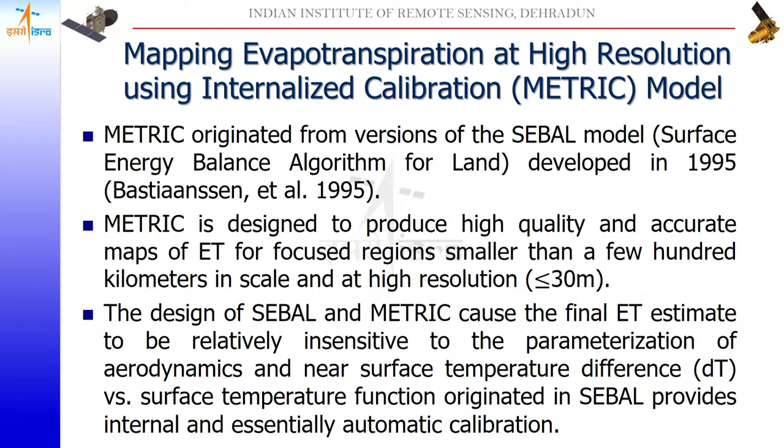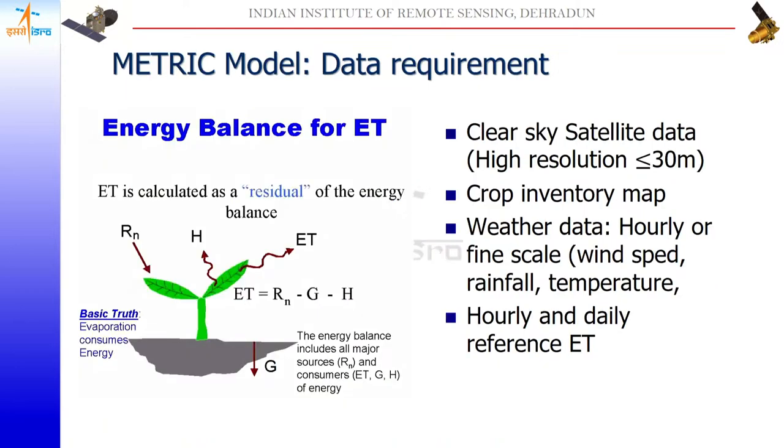In this model, basically it is an upgraded or improved version of the SEBAL model. Earlier, Professor Bastiaanssen in 1995 developed a model named SEBAL, which is Surface Energy Balance Algorithm for Land, which is a completely physics based model, where they determine the hot pixel and cold pixel, basically known as anchor pixels, and with internalized calibration to finalize the hot and cold pixel basis, they ultimately define the H and LE components. How do they define the H and LE components?